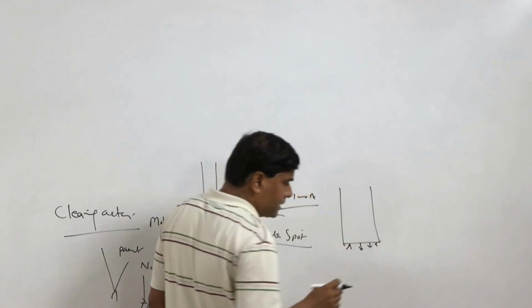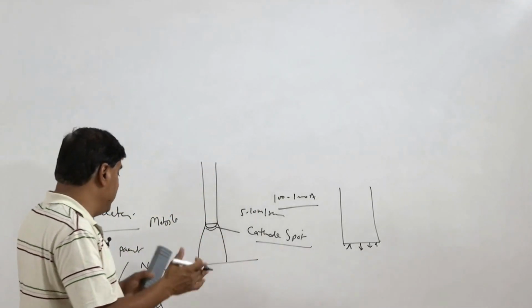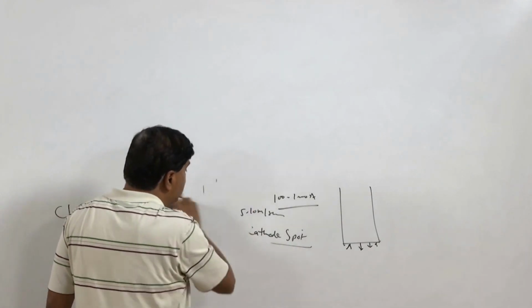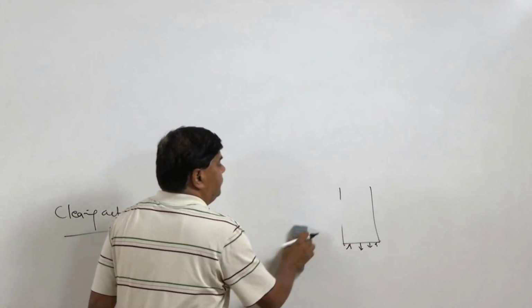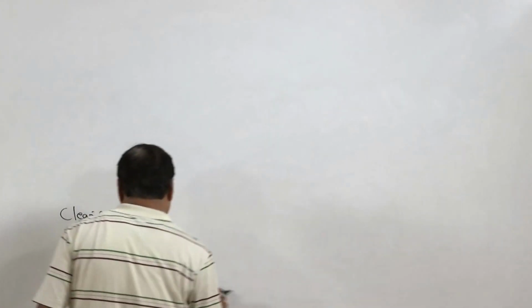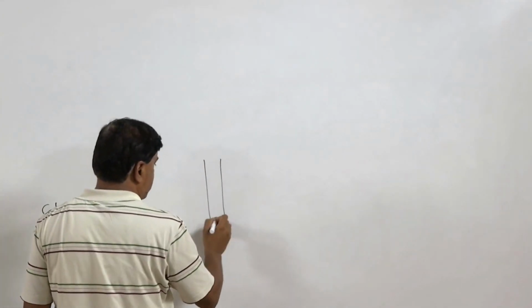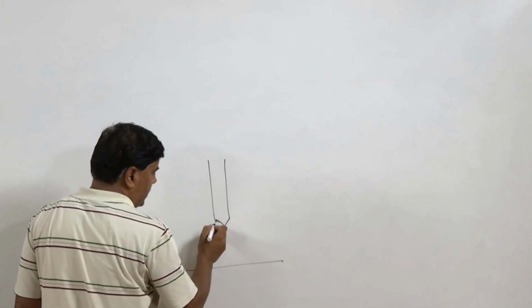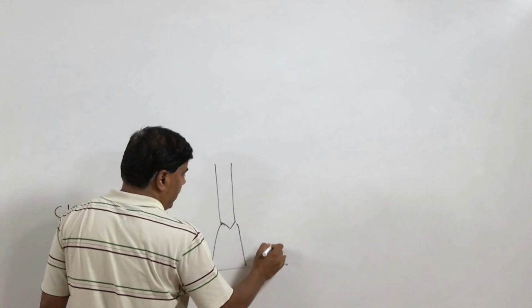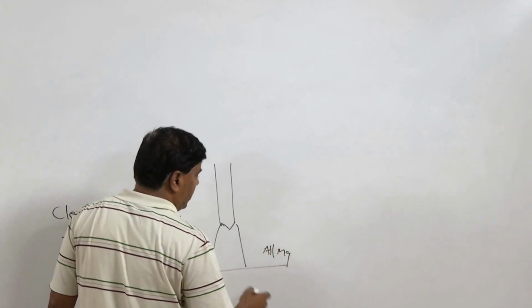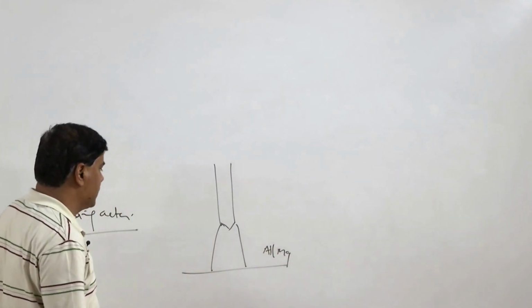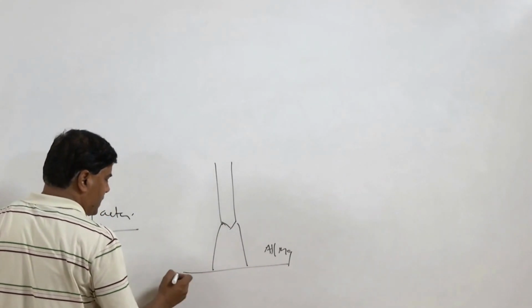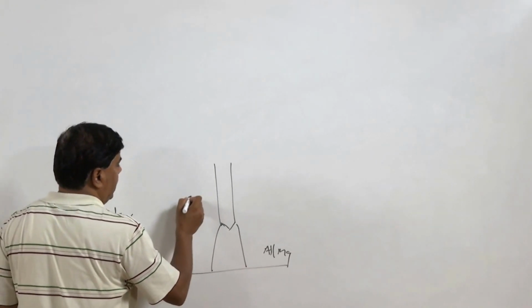This concept is exploited from the cleaning action point of view, in the sense that if the workpiece is made cathode and a mobile cathode spot is formed, like say this is the tungsten electrode or any other process electrode, and aluminum or magnesium is welded using the GTAW process, making the workpiece negative and electrode positive.